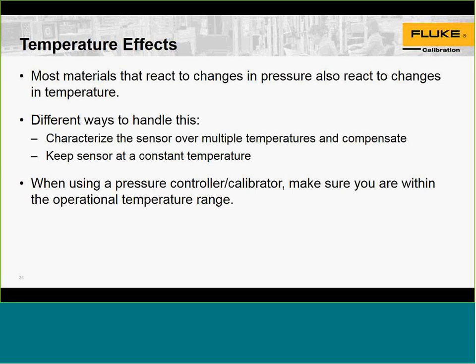When using a pressure controller calibrator, it is important to use the controller within the operational temperature range that it was characterized in. You don't have to buy a pressure controller and characterize it yourself. The sensors are already characterized and assigned some limits on the temperature range. And if you're outside of that temperature range, we provide a specification that you should expect to see outside of that range.